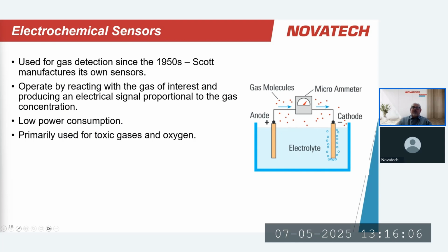The concept of an electrochemical sensor is actually pretty basic. I think the analogy I use is it's like a battery. It's like an Energizer battery type thing that's missing one component in order to operate. So what you have is a container or reservoir of some kind that has an electrolyte and an anode and an electrode of specific metallurgy, and the electrolyte is of a specific chemistry as well. And they're designed in such a way, or the materials are chosen such that if a certain gas is present in the atmosphere, when it diffuses into the electrolyte, it will allow current to be generated.